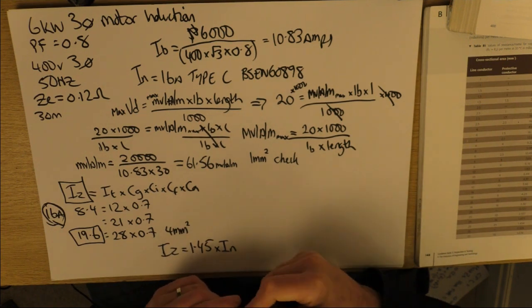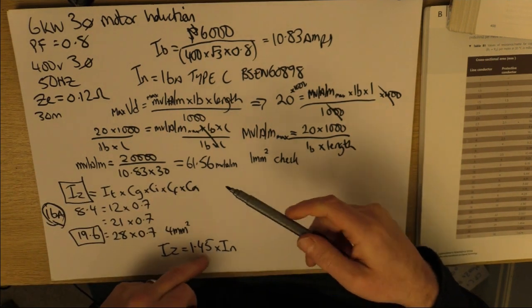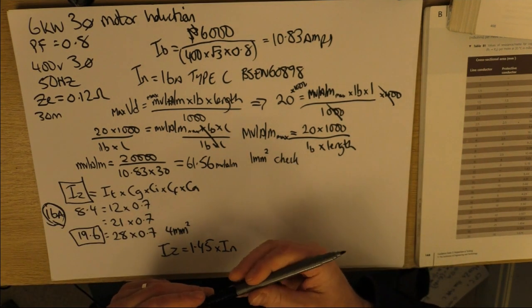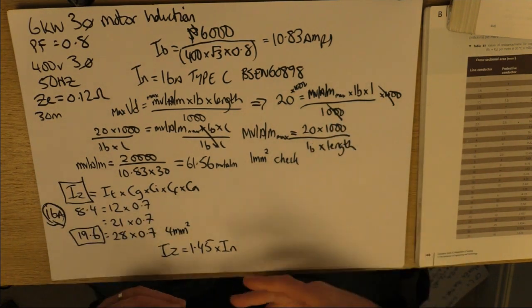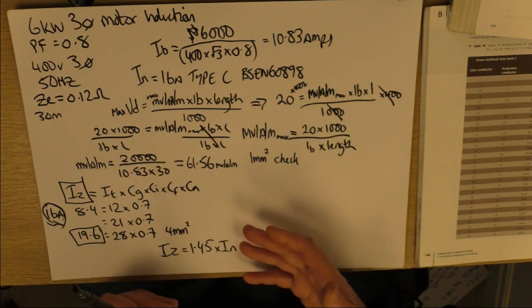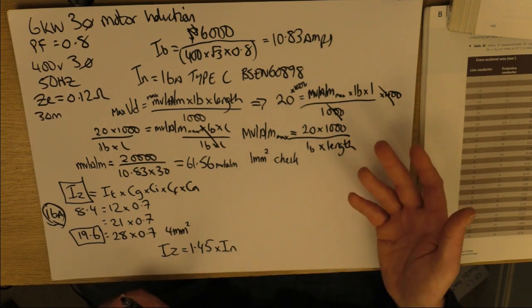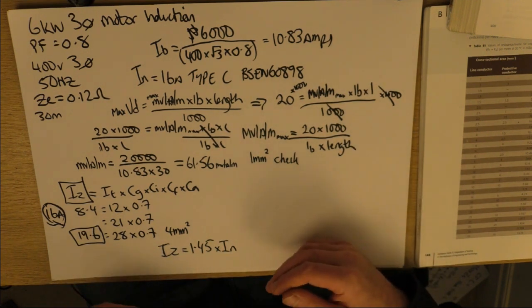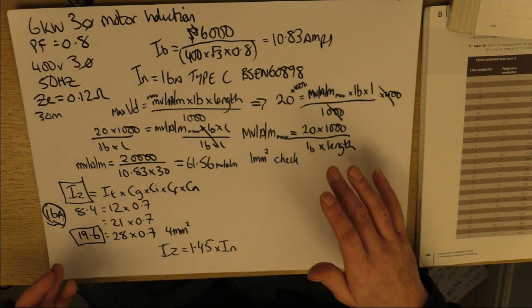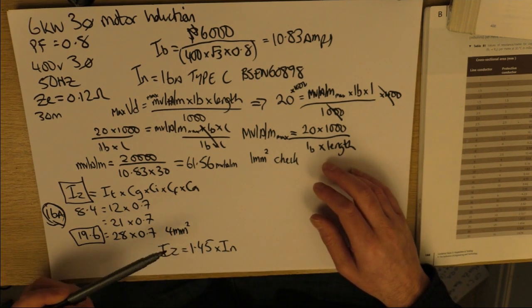And in that time, you might get a problem with the circuit. So it's normally going to be things like socket circuits, where you don't really have a lot of control or knowledge about what they're going to plug in. So places like care homes in the winter, you know, they're going to pull out all them heaters, they're going to plug them in. Same with meeting conference centres, places like that. We don't know what they're going to turn up with. So, you know, you need to consider this.